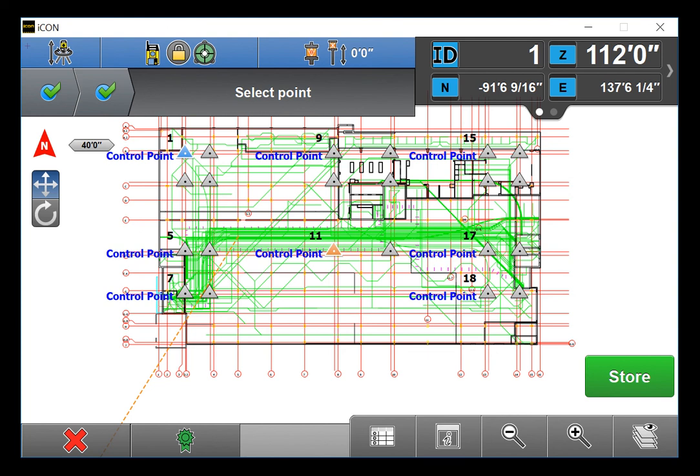Once your horizontal residuals are within tolerance, click the green check. When you are returned to the map view, you will notice another green check next to the green ribbon. Clicking the green check here will accept the stored measurements and establish the coordinates and base angle of the total station. You may click OK at the next prompt accepting this total station setup. You will then be taken back to the Layout Points map view where you are prompted to select a point to stake out.